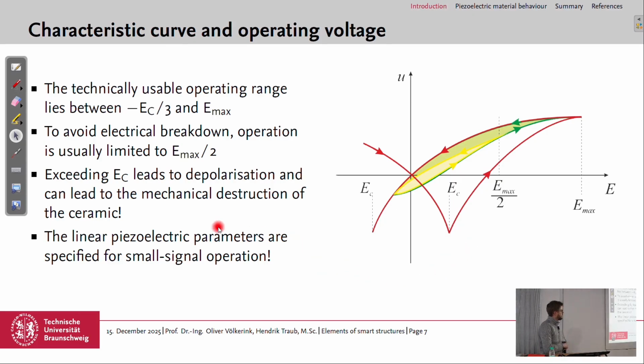So we are now going to have a look at the linear piezoelectric parameters, which is specified as small signal operation. So we linearize the behavior and do not take into account this nonlinear behavior and this hysteresis effect, for simplified modeling.